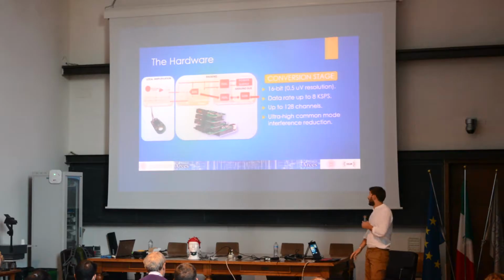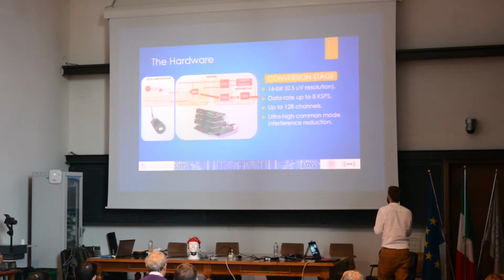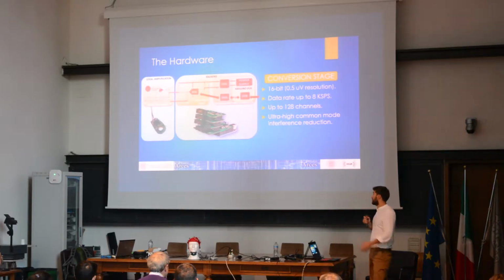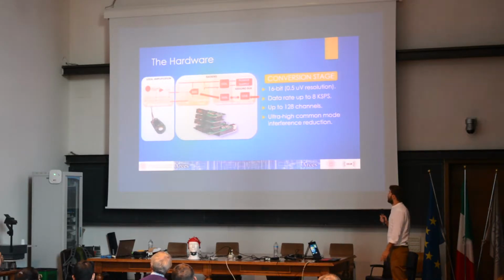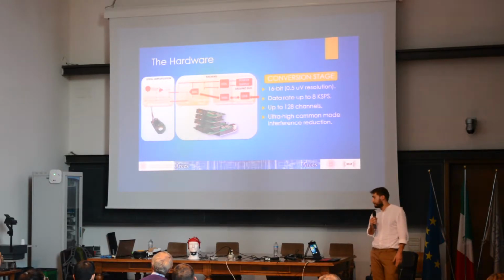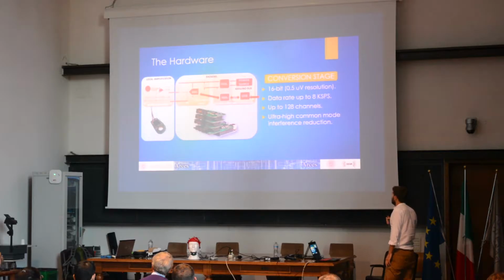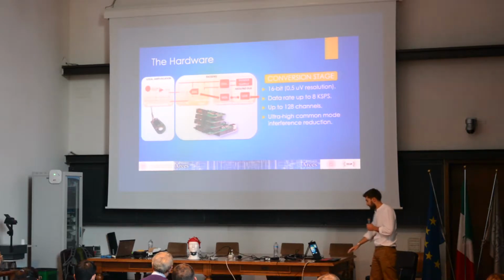The conversion stage is based on a 16-bit analog front end from TI. The system is modular, so you can connect more chips, and you can reach up to 128 channels. This kind of system has an ultra-high common mode rejection ratio for interference.